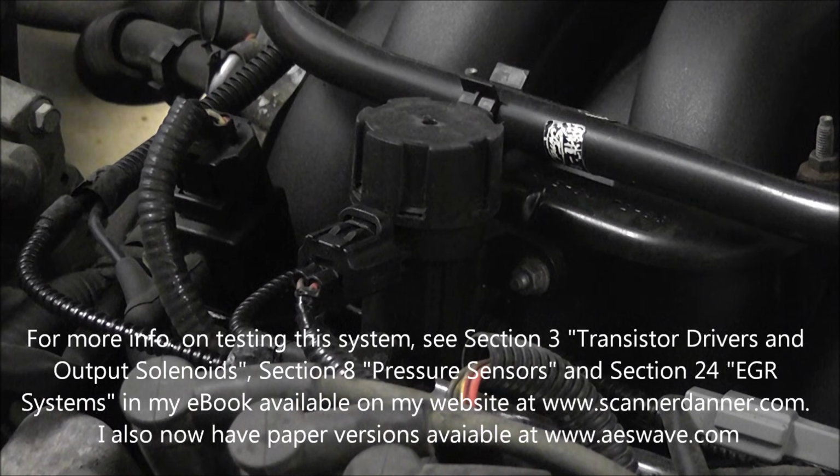This is something that's important that you want to research before you do testing like this, to know whether or not it's power side or ground side switched. I know these Fords, it's ground side switched. We're going to do the test now. So I'm going to take a test light to ground there. I'll get you a shot of the location of the valve too.